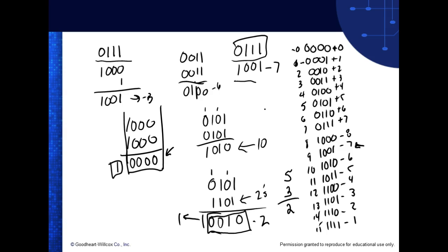So basically all the processor would have to do is invert the number, which the processor can do real easy, and then add a 1 to it. And that's the way it does math. So the processor does it with something called 2's complement. What we do though is we sacrifice our most significant bit as our sign bit. So if I'm doing signed math and it's got a 1 in it, it's considered to be a negative number. If it's got a 0, it's considered to be positive.